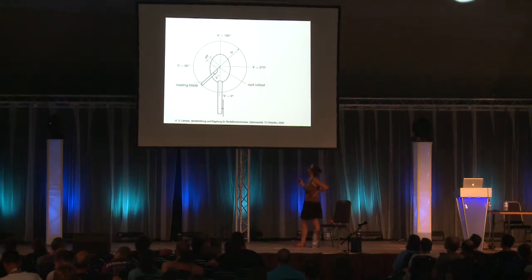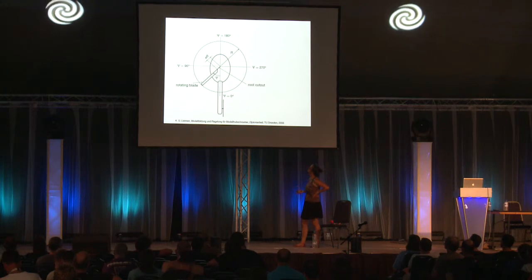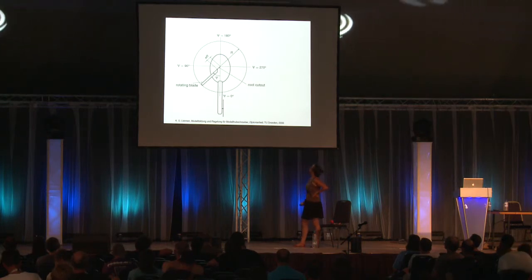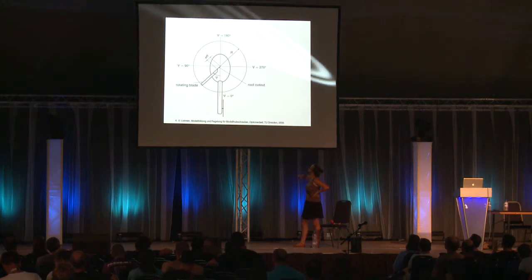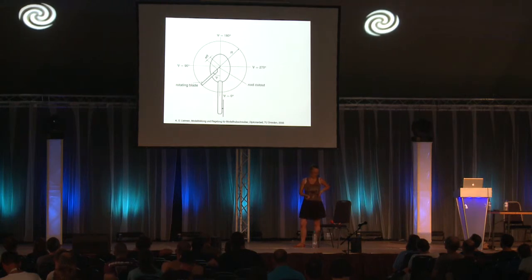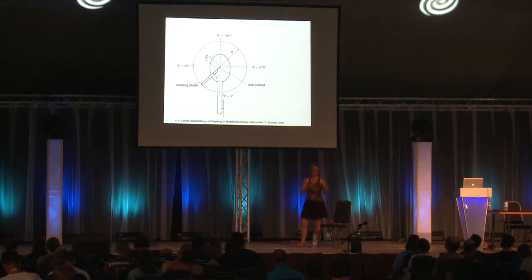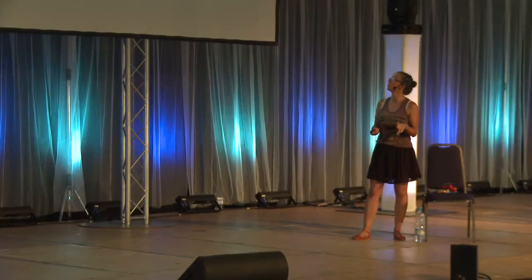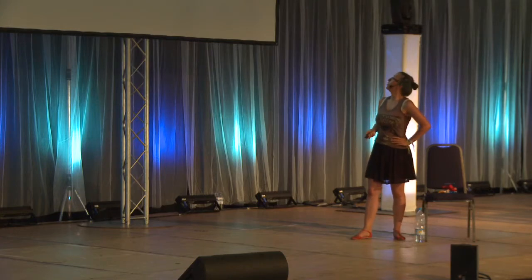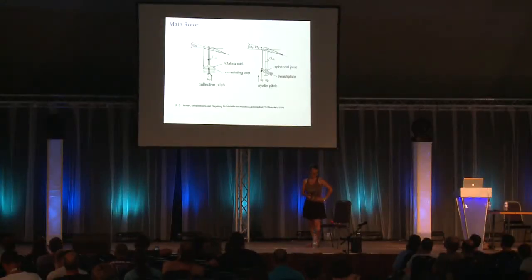And if you integrate over the whole, I'm sorry, it's not working. If you're integrating over the whole circle, you get as well the generated torque at the considered rotor. So taking into account the number of your blades and the number of your rotors, you can simply compute thrusts and torques. We'll see some formulas later, because they are not of interest right now.